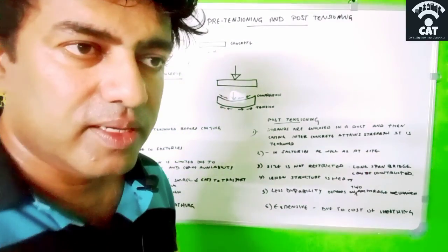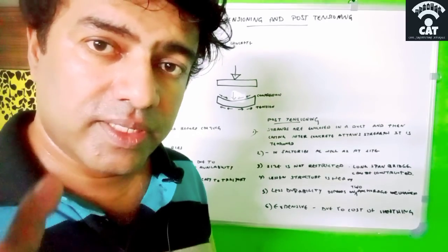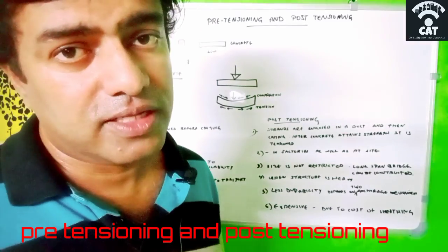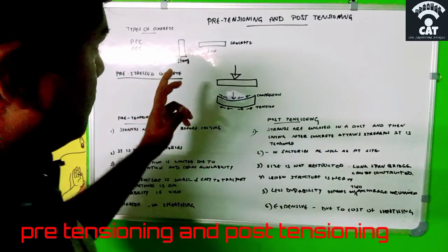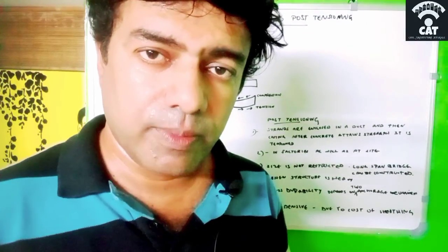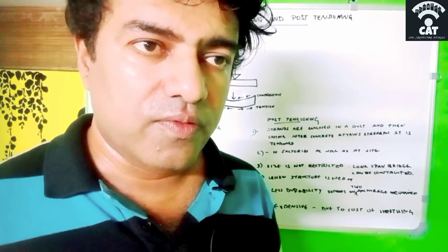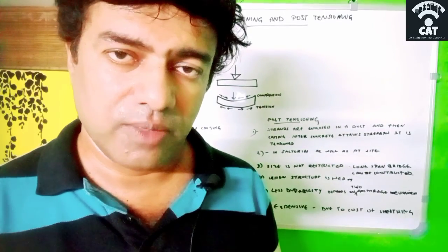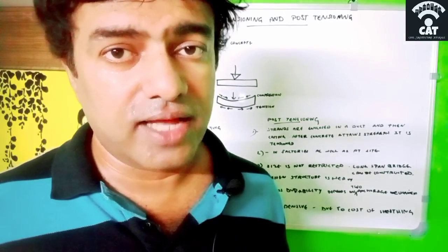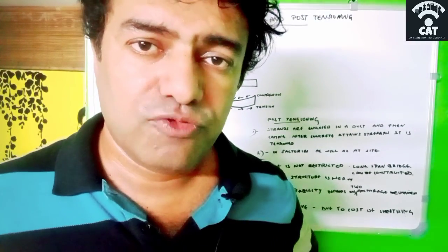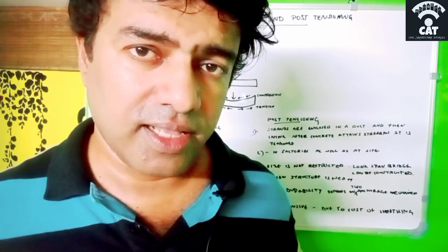So what is called pre-stressed concrete is this thing, and it has been done in two ways, that is pretensioning and post-tensioning. Pretensioned concrete and post-tensioned concrete. So pretensioned concrete is the concrete in which that steel member, called strands or tendons, we are pretensioning these structural members, the strands, first, and then only the casting is done, then only we are applying the concrete.